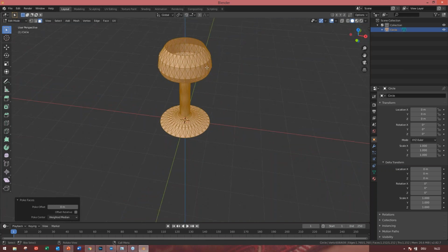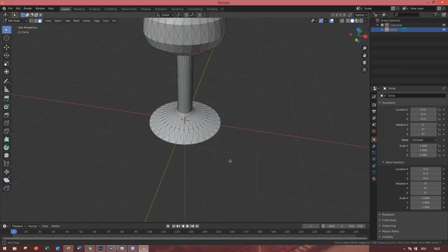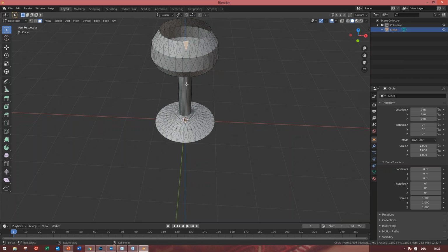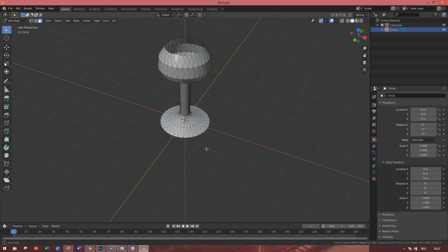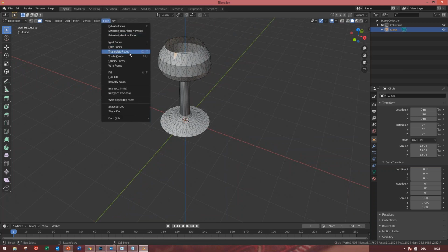That's also possible and that will also work because we will have these single little faces in triangular. So this is also another option, but you will add for this a lot of vertices. So it's not needed to have poke faces for the Warper. If you want to save the performance, use just the triangular option here for the triangular faces.